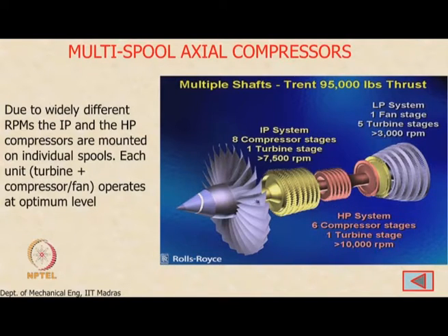We actually allowed different parts of the engine to run at different speeds, again for the same reason, because the fan was really quite large and the centrifugal stresses would have been very large. So we said that the fan has to spin at a slow RPM, whereas the high pressure compressor has to spin at a much higher RPM. So then we segmented the engine and mounted them on different shafts, so that this ran at a very high speed, this ran at an intermediate speed, this could run at the lowest possible speed. But that was 40 years ago.